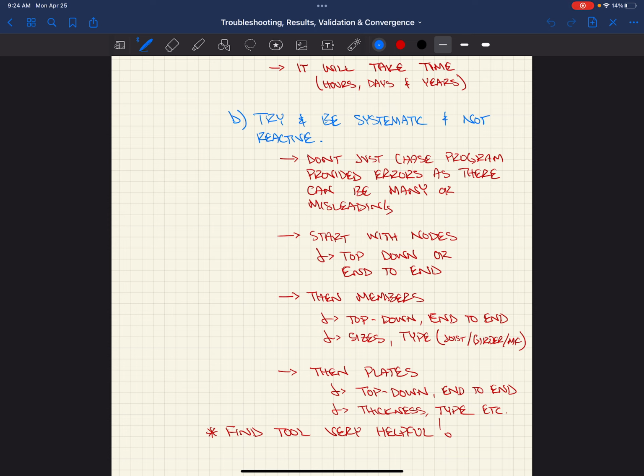All right, so in the model view, there's this little cut feature in the project manager. It'll work. Oh, it's got to adjust to the screen size. All right, if I was going to, well, let me go back here, model filter. I want to show the nodes finally. So I got all my nodes here, right? Got all my plates, I could turn all my members off. If I wanted to cut and I wanted to look at all the nodes at the ground floor, right? I can go through and I can cut my model so that it only shows the bottom nodes.